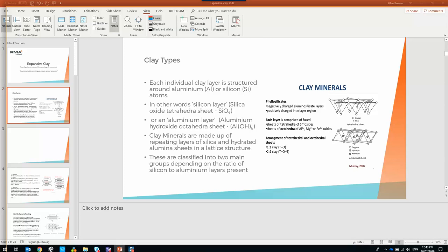Here's an example of one, Craig will recognise that, that's McLean Farms grading floor. That's the former tube liner. We just come out of the ground, and that forms our column to get it out of the ground. But below that, there would be an overbore and backfill with gravel. So that one's a Bondek slab, obviously.